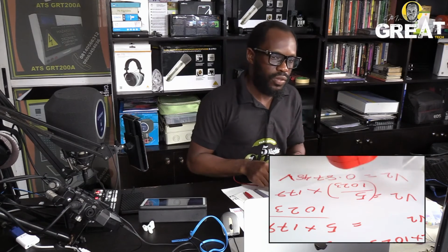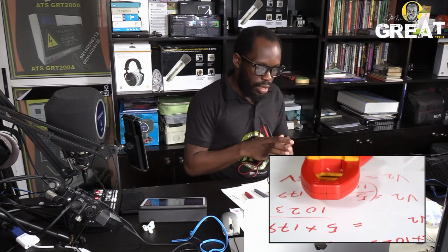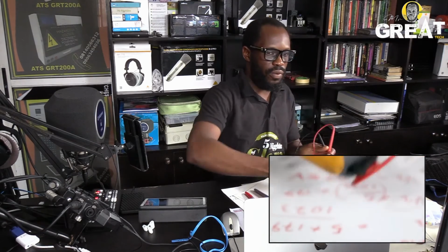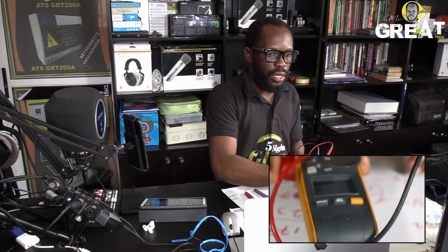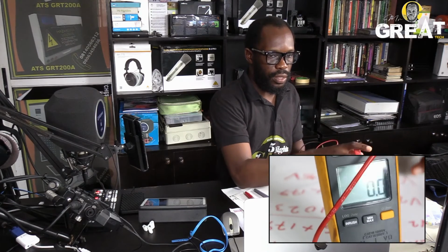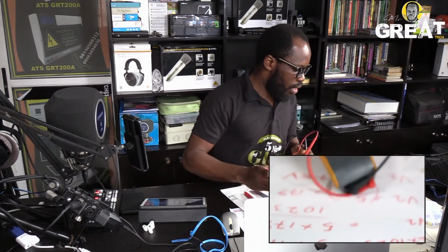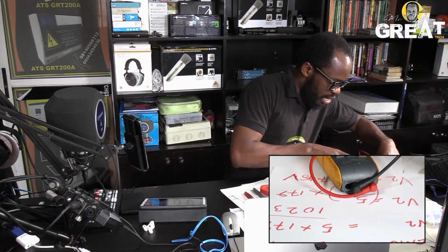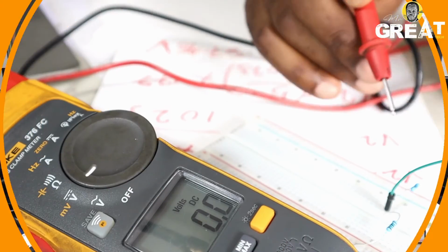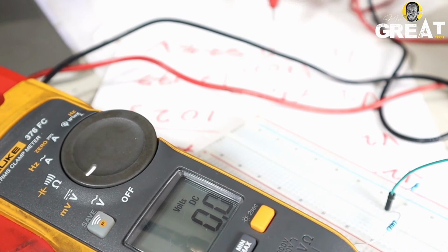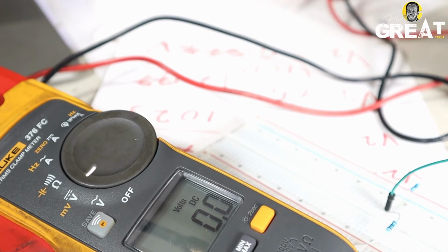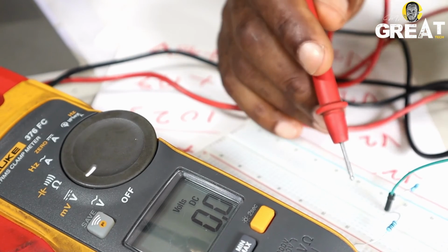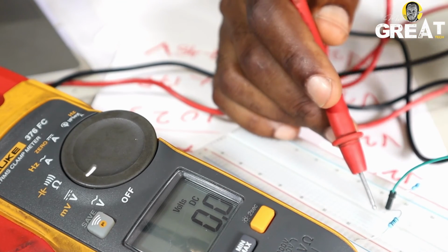Okay, so now let's go straight to the point, so that we can see how to measure and read the voltage. Now I can see, yeah, this is 0. Now we are going to read across V2, which is what the Arduino is actually measuring. So what did we get in our calculation? We got 0.87 volts. So now we measure the voltage across V2, which is the 100 ohms resistor.